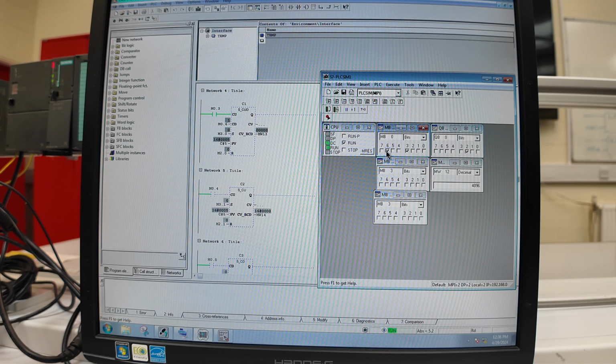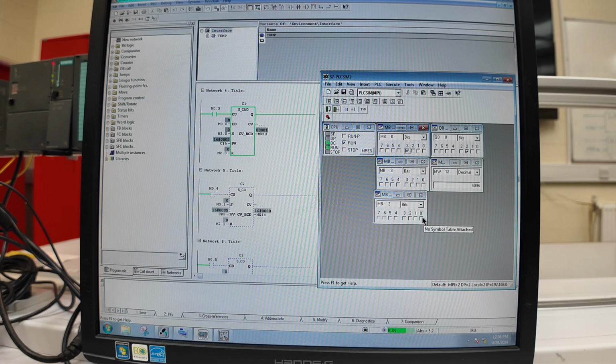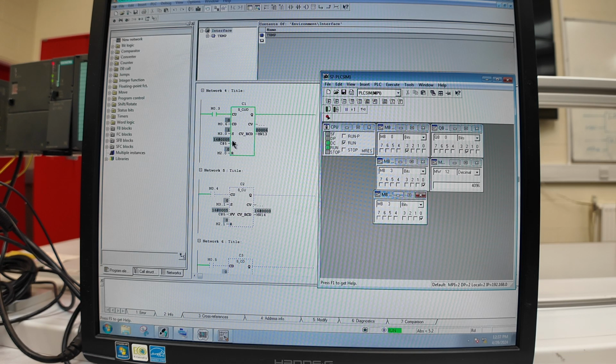Our output is not set anymore, our output is just set if our counting output is higher than 0. Now we have our value at 1, and if I'm activating now the set pin, then our output increases by 5, because 5 is our counting value here.